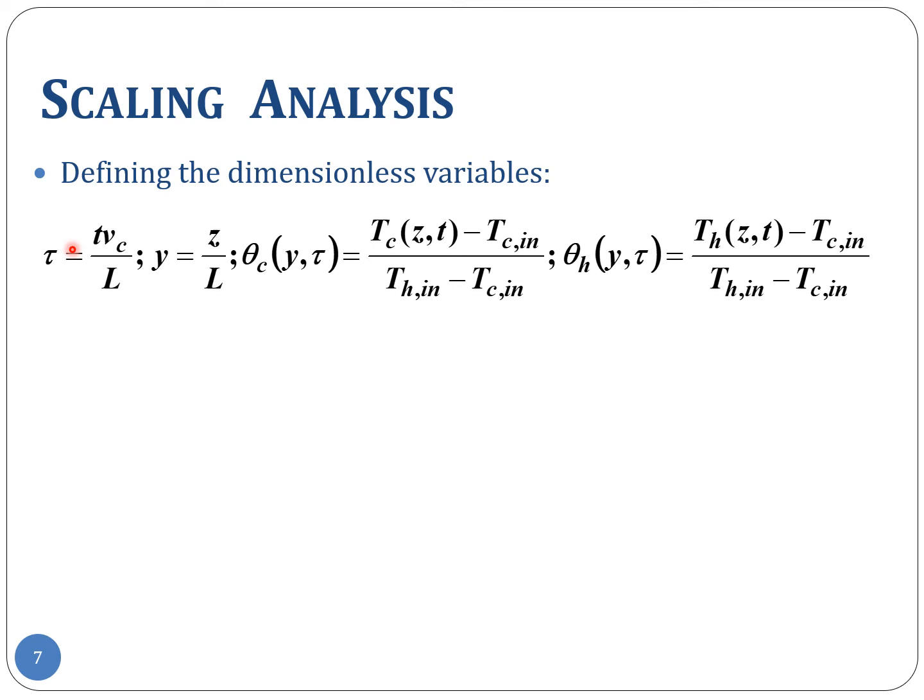One could write so many of these quantities for each phenomenon, oftentimes competing with each other, that together in some combination determine the behavior of the overall system, in which case here is the double pipe heat exchanger, and particularly the heating of the cold fluid in the double pipe heat exchanger. That's what the model equation is for. So the entire question of how much the cold fluid is going to be heated is answered by understanding how these two competing phenomena combine with each other.